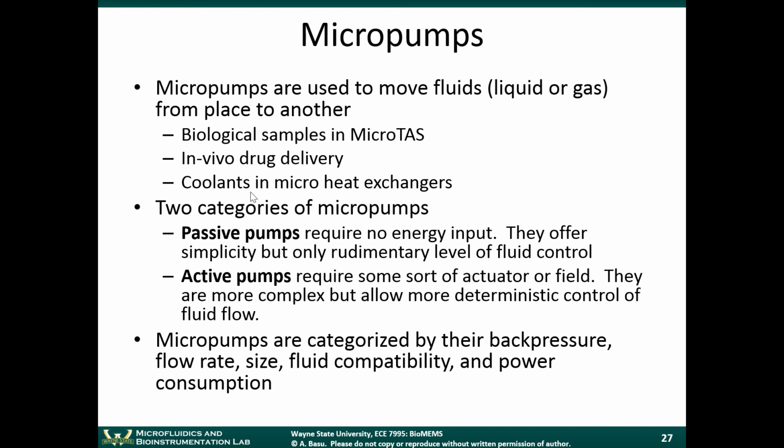There are the passive pumps, which require no energy input. These types of pumps offer simplicity, but only a rudimentary level of fluid control. The active pumps, by comparison, actually require some sort of actuator or field. You need to put energy into the system somehow. And these are a little bit more complex, but they also allow for more deterministic control of the fluid flow.